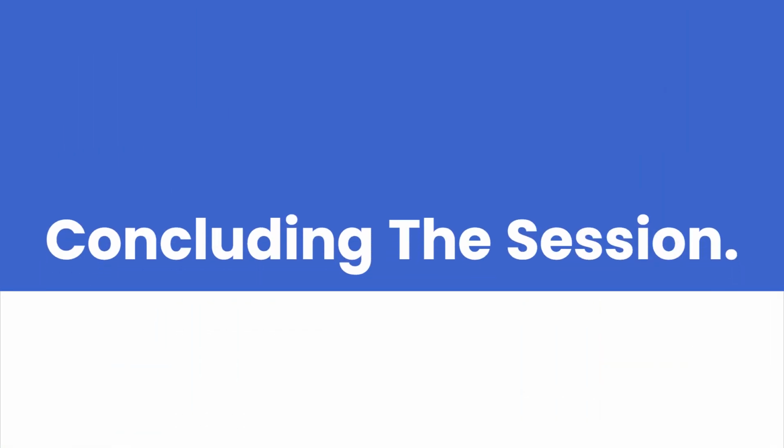So with this we are now concluding this session in which we have learned three different tools such as rib, web, and emboss. These are very effective and efficient tools to change and modify as well as give strength to the objects. Also, interior details to various accessories and furniture such as cabinet, desk, etc. can be developed using the web feature. Also, emboss is a tool similar to extrusion in which we can make extrusion or extrude cut of the text-based entities.